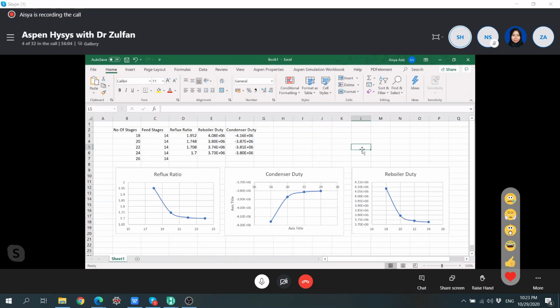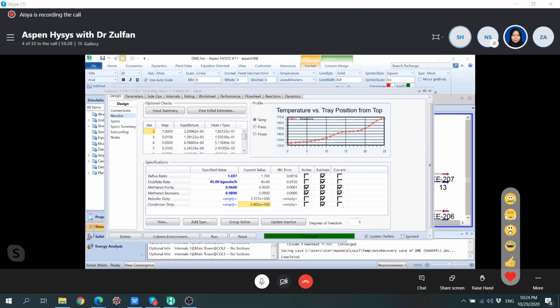For that, there is an online source, like in this Turton book, they have the cap cost. You can Google the cap cost Excel file, specify the column sizes, and it will give a rough estimation of the cost for different numbers of stages.